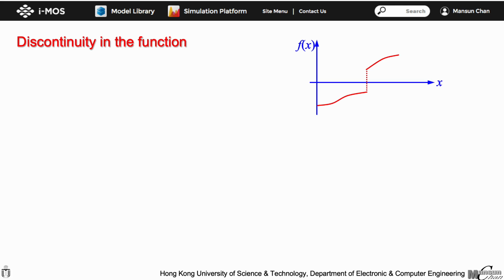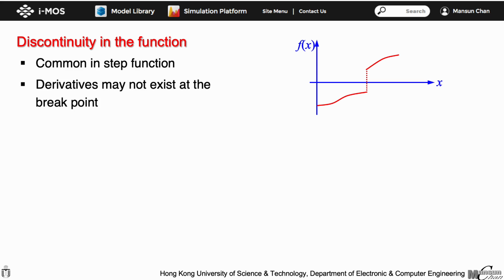More seriously, some poorly formulated models may have discontinuities in their current-voltage equations. It may not be caused by the device model formulation itself, but some devices like a switch do have abrupt transitions described by step functions. In this case, the solution and derivatives at one end of the breakpoint are inconsistent with the other end, leading to oscillations.